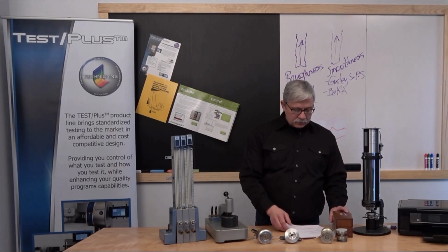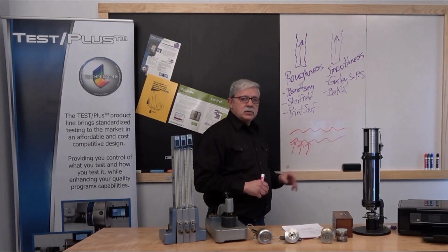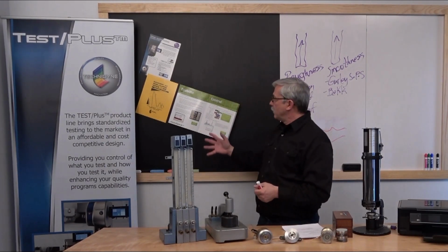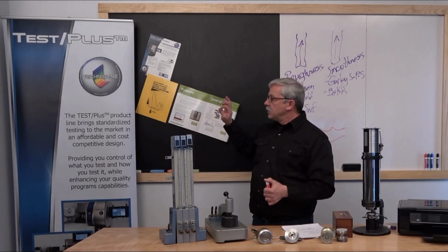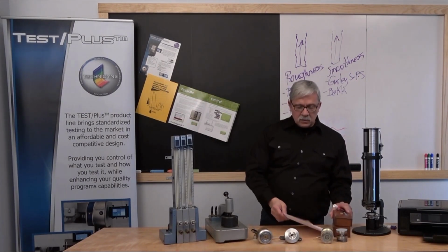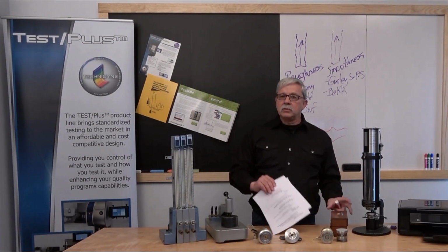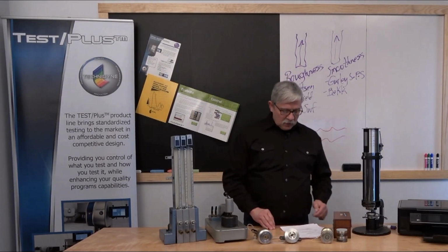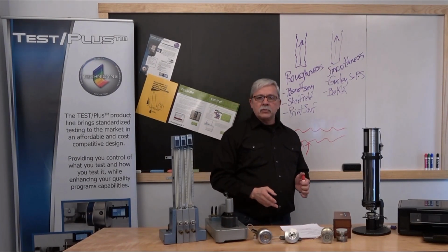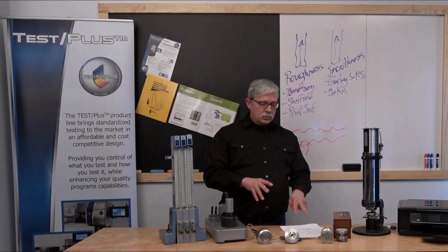All right? So if you think about these undulations, obviously we want these undulations to be as uniform, but also as small as possible when the application is appropriate. So if I want a high gloss document like this, that surface I'm probably going to coat, but that surface really has to be a lot smoother than the print paper that I'm going to use in my printer or the copy paper I'm going to use in my copy machine. It does turn out, again, like I said, it's a very good predictor of printability, a very good predictor of, let's say, surface friction for transporting of the paper.